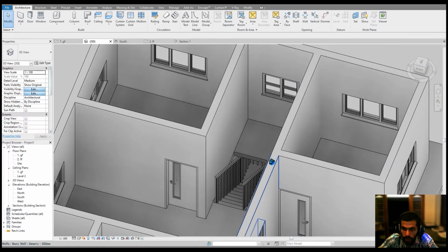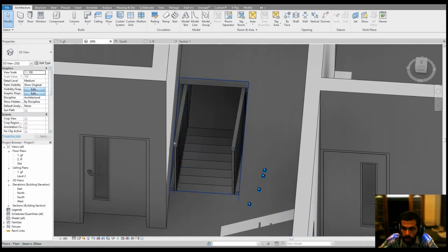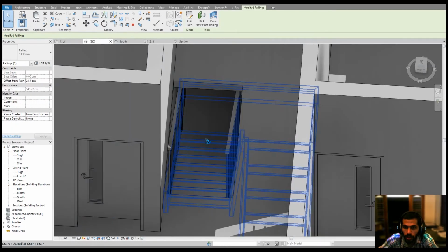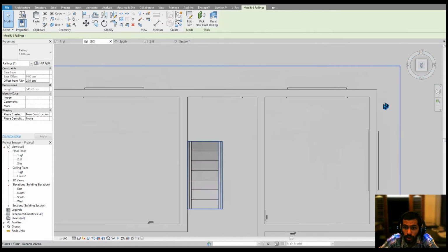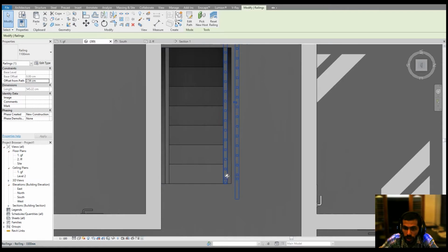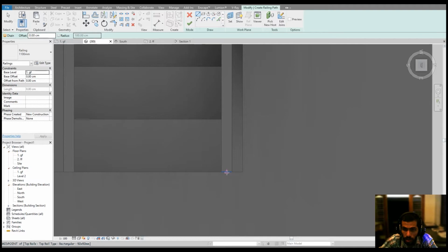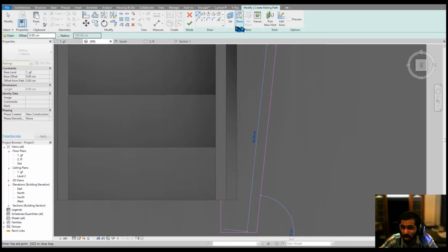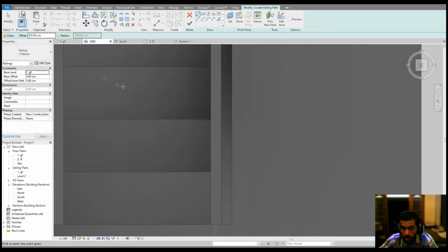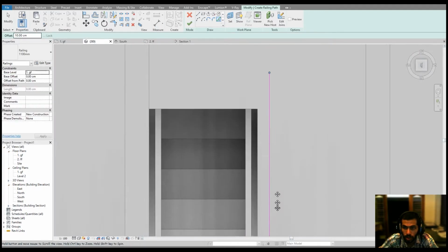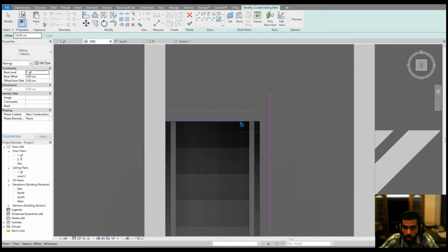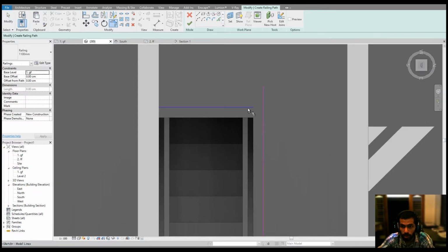So you can see that the floor is right here, and now let's connect this handrail. Get into the 3D top view, and let's draw a railing right here. The railing should start from here, and you can either make use of offset or pick line. Maybe I'd like to have 10 centimeter and get into the pick line. One goes right here and the other one goes right here, and we'll trim it.